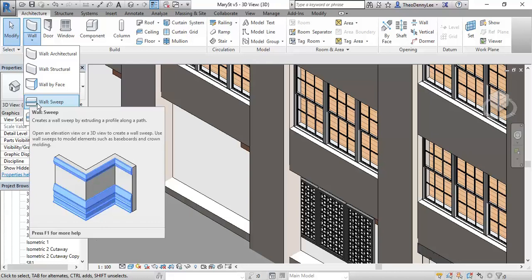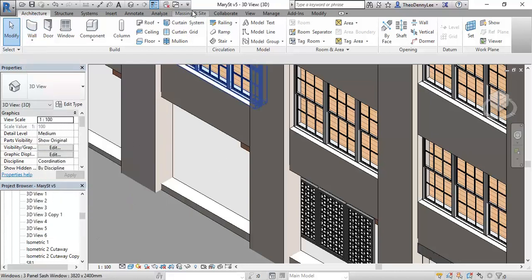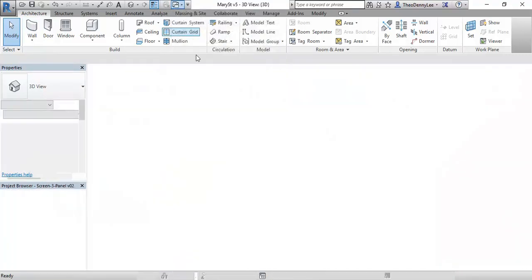Yeah. And so just to finish off there though, the wall sweep tool's pretty good, but I don't really like it that much, just because it doesn't work very well if you're doing it on two sides. So say you've got an interior wall, and you want to put a cornice and a skirting on both sides of that wall, which is pretty common. It's very difficult to do that with the wall sweep tool. So sometimes you've just got to do one, and then you have to model the other side using a regular sweep. So it's still really important that you understand the sweep tool. And so again, I'll give you some time to work on that before I go any further. But then just want to point out those other tools.